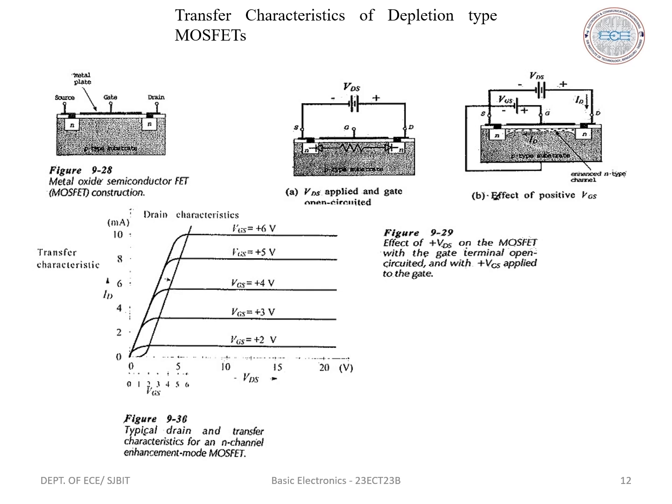The MOSFET conducts current between the source and drain. The path for current between source and drain is called a channel, and the width of this channel is controlled by the voltage at the gate terminal. Next we will consider the types and working of depletion mode. Here the characteristics of a MOSFET are similar to those of a JFET. That is, when VGS is equal to 0 volts, ID equals IDSS, and when VGS is less than 0 volts, ID will be less than IDSS.